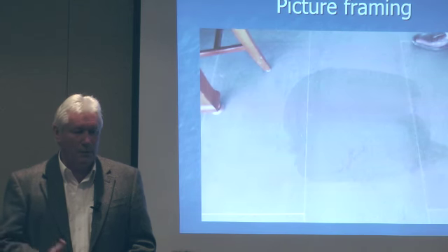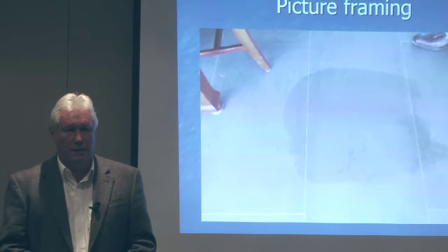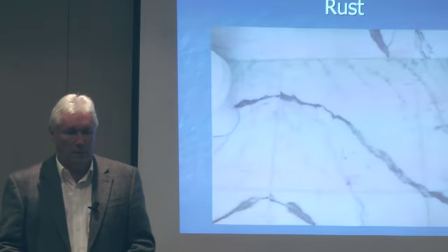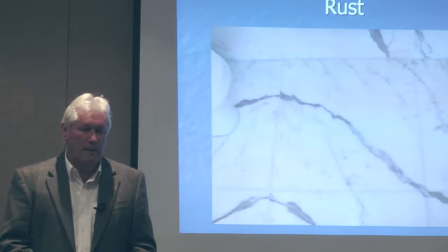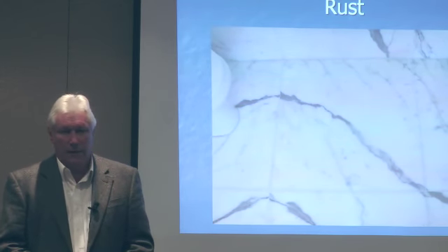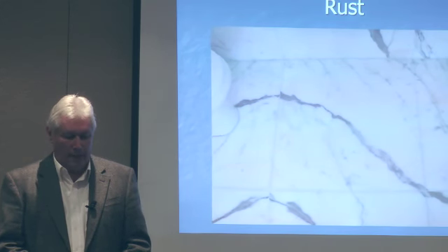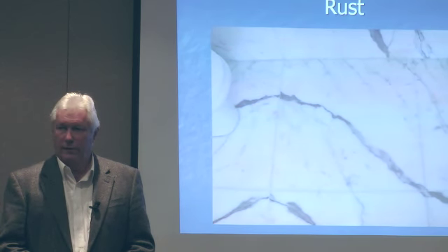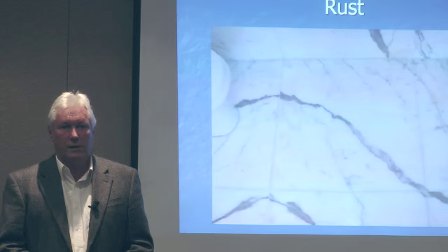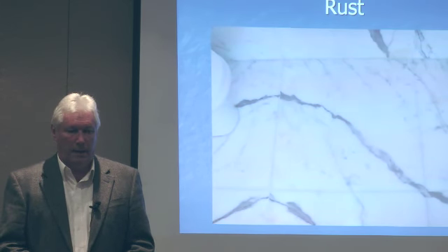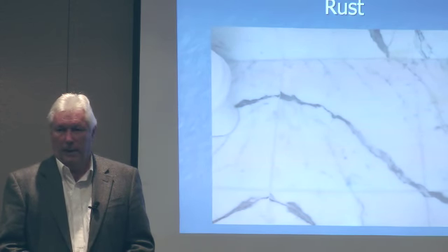So sometimes it might be a case of making sure that the tiler, if you're using a coloured grout, grouts all over the tiles and doesn't just grout the edges. A lot of problems can come up. With white marbles in particular, lots of light marbles, we can have traces of ferrous oxides in there, and that means that at some stage moisture moving through that stone and then coming in contact with oxygen is going to give you rust, and so we can get some very high quality, beautiful, in this case, vein matched stone, and we've got a problem because it's going brown and very hard to treat.